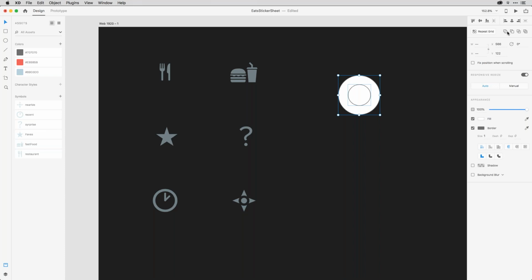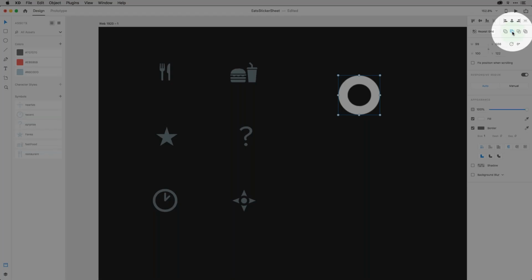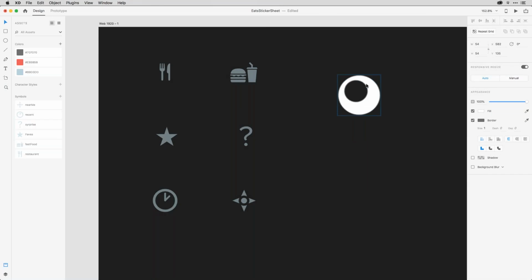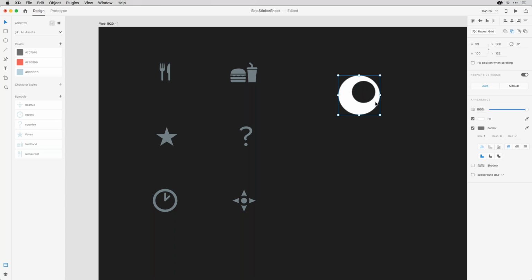So I've got this area just at the top of the screen here where I can create Booleans. Great thing is, just like shapes mode in Illustrator, these stay live for their entire duration. So if I needed to get in there and do something, I'll just double click, move that around. There you go. Let's go with that. Then just come out, and there you are. There's my Boolean. So I've got that going like so, and I'll add that by clicking the plus at the top here and then just rename it as required. I'll undo that so we've got back to these things.